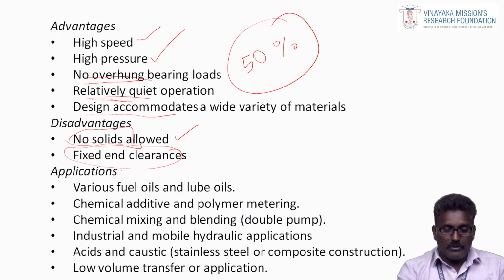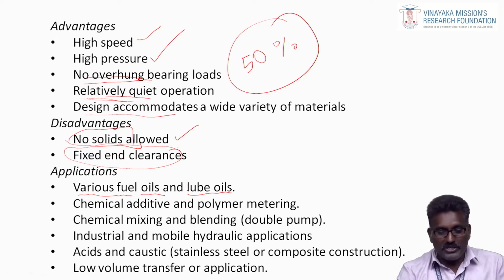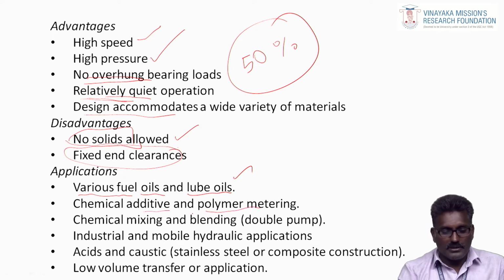This pump has huge applications. It handles various fuels, oils and lube oils, etc. Even many of our automobile IC engines have a lubrication circuit, and that lubrication is pumped by this kind of pump, mostly gear pumps. It is also used for chemical additives, polymer and chemical mixing and blending applications.